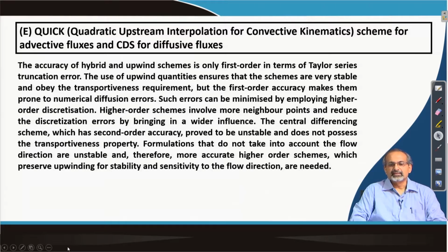So, if we were to extend this problem to a 2 dimensional problem, how would numerical schemes like QUICK or first order upwind scheme, which we have already discussed, work? If you recall, we have already learnt a number of techniques now. We began with the central differencing technique, then we went on to first order upwind, then we looked at the exponential scheme, and from there the simplified versions, the hybrid and the power law scheme, and finally we looked at QUICK. Now, for the 2 dimensional convection diffusion or advection diffusion problem, we are just looking at how QUICK and the first order upwind scheme would work.